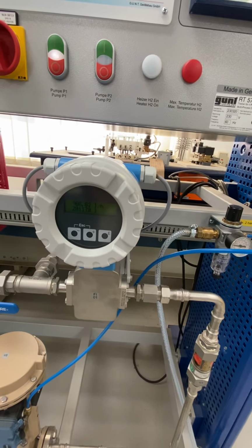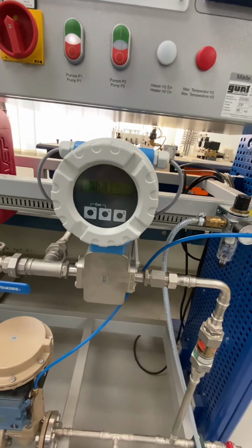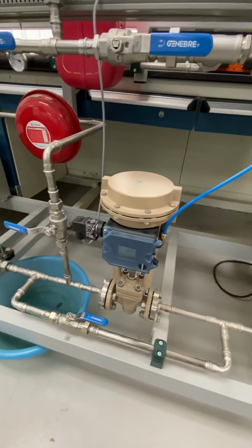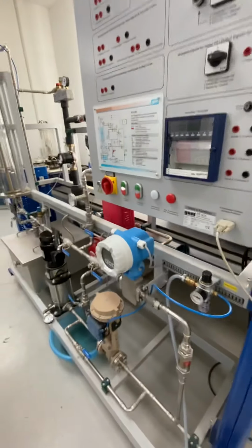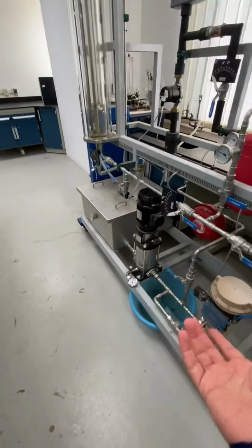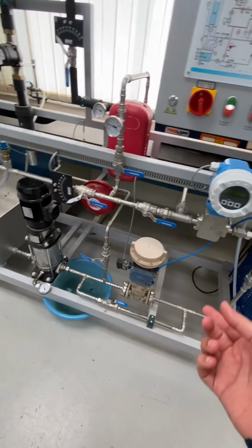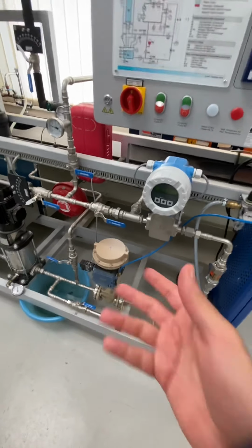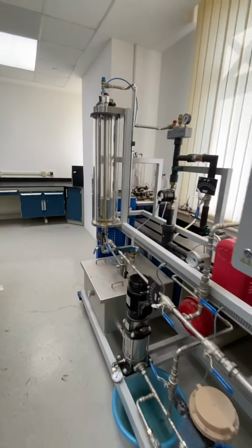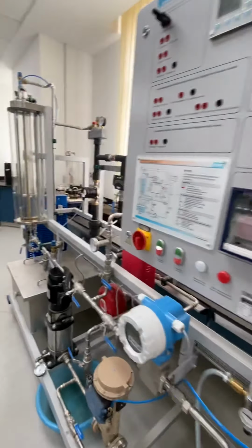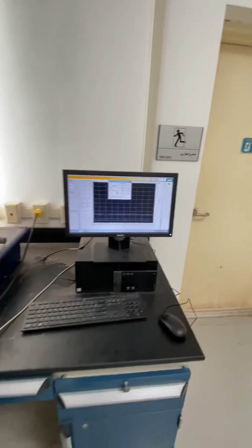Yeah, there is almost no change in the flow rates. So it was almost around 900 something. But again, as I said, guys, if the pump was running at a much higher speed and the control valve was suddenly opened, now we will have two valves being opened. That means more flow into the tank, and you'll see that the output signal will start to decrease.